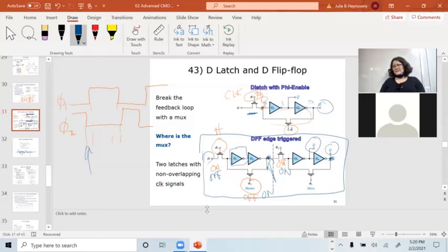So just to guarantee that you have a strong signal when you don't have control over where your outputs are going. They could be going to a crazy printed circuit board designer who thinks he can drive a motor off of his Arduino. You put a big buffer there so you don't damage your own circuit.